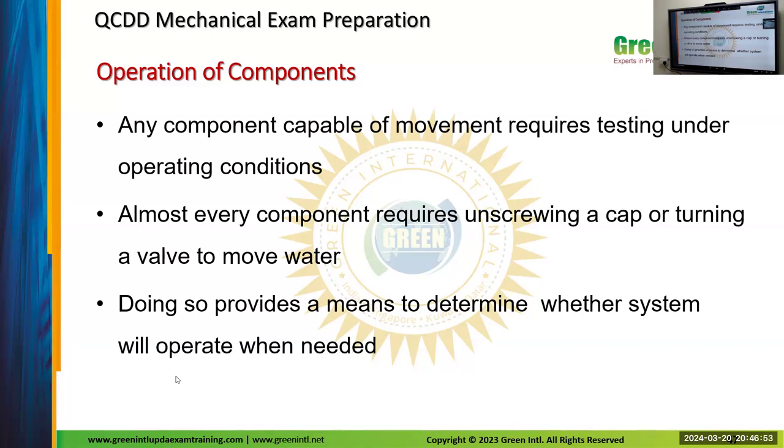Regarding maintenance, it is 2 or 3 pages. You can expect long pages. Each section gives hose reels, hose, standpipe system. But in NFPA 24, I believe, you will have a consolidated inspection, testing, maintenance plan. So if an inspection, testing, maintenance plan is asked, go directly to that section and refer. If it is not given, then you can come back to this section. NFPA 25, yes, inspection, testing: it will give you only a few portions here, but NFPA 25 will give you the details of all this. Okay.